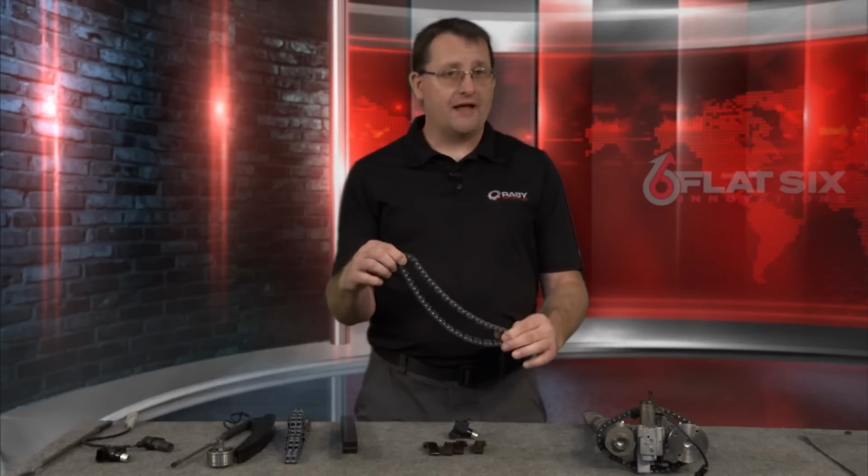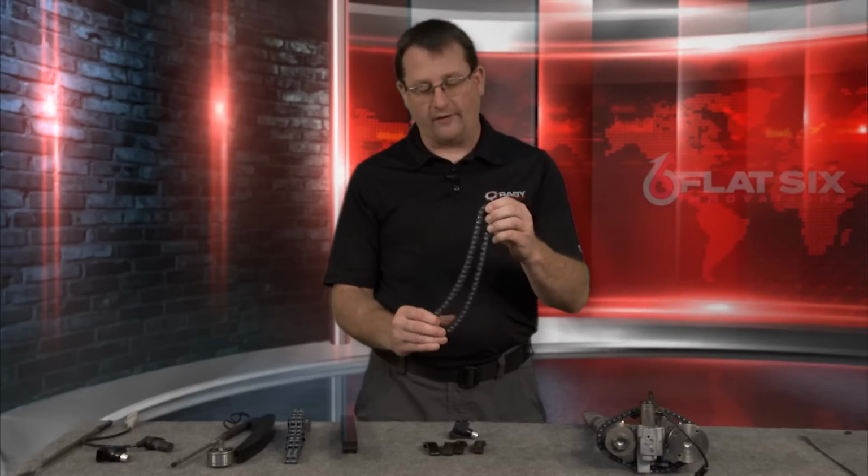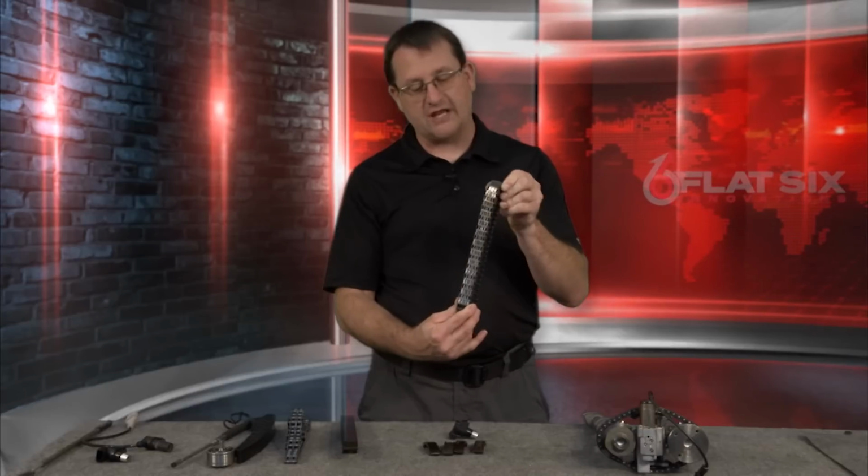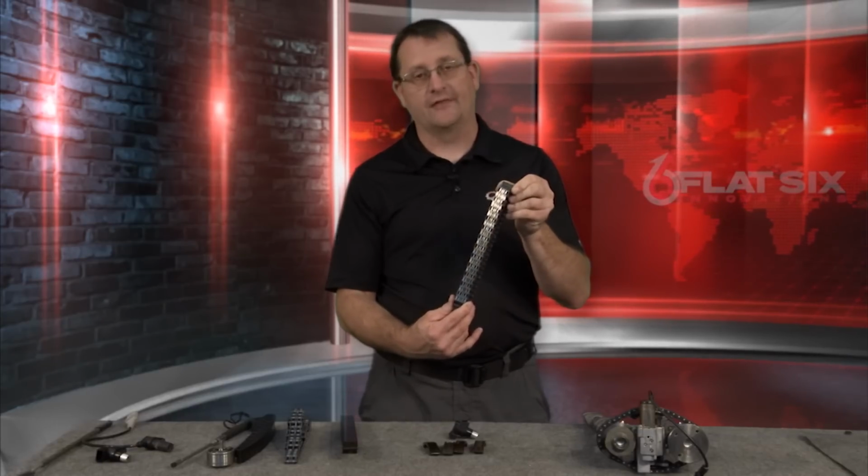Now what's unique about this one is the fact that this one will play into the deviations on both banks equally. So if this chain starts to wear, okay, and this one does have some wear on it, I can tell by how much it deflects. That's one way we can grade these, is how much that chain deflects, and I've actually got a measurement for that.